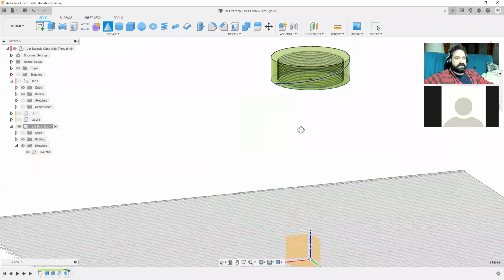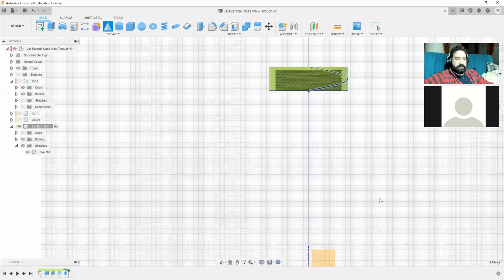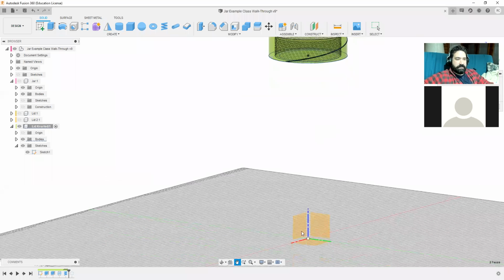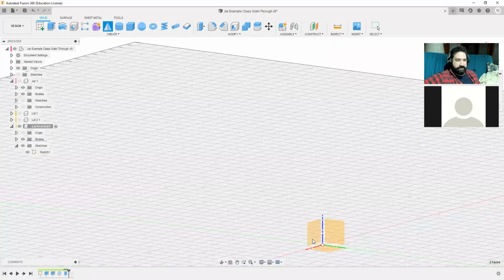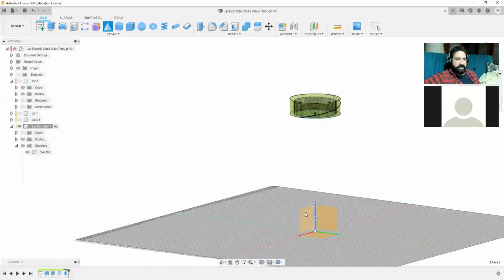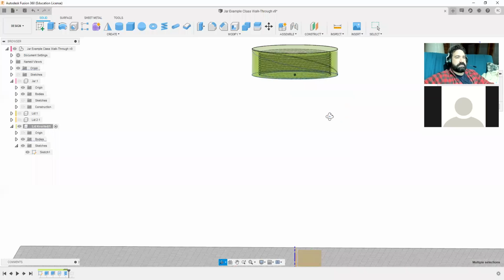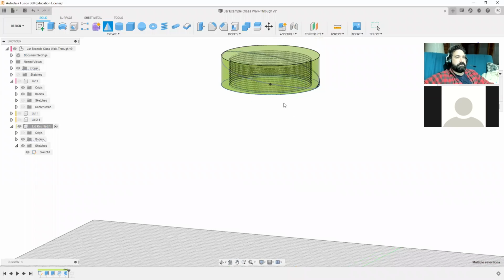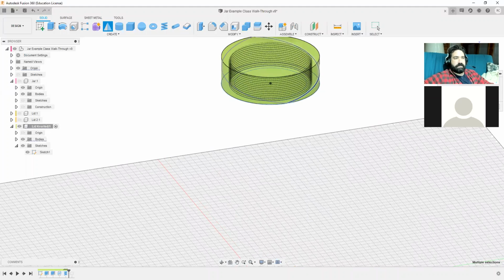All you have to do is tumble around your work. Okay, right plane. So I'm going to use the XZ plane down here in my origin. I'm going to select that, if it'll quit bouncing around on me. There we go. Now you see it has created a mirror on the other side of that cylinder. Cool. That's all I want.